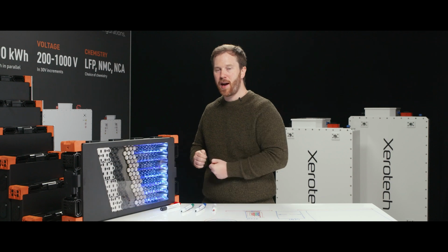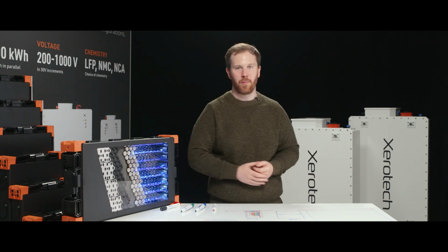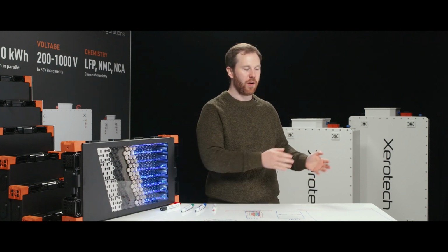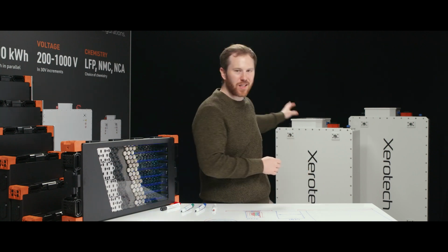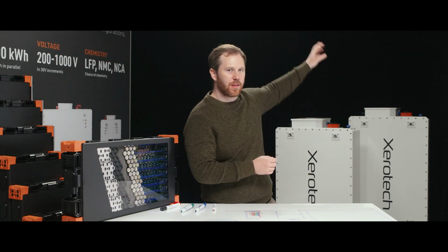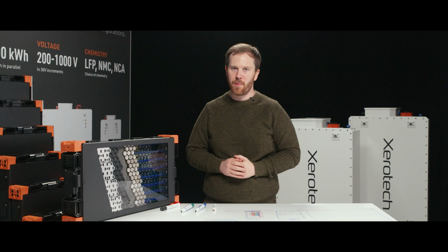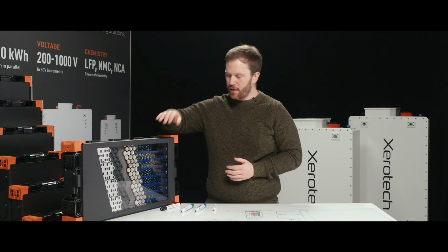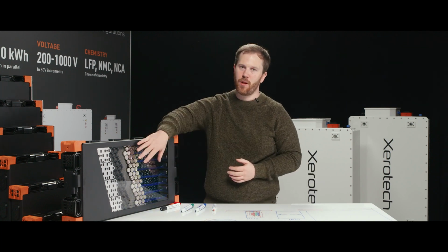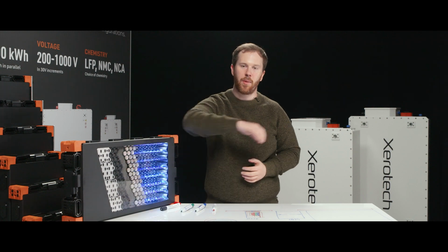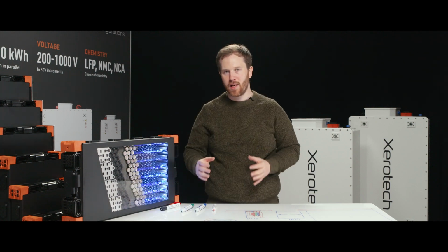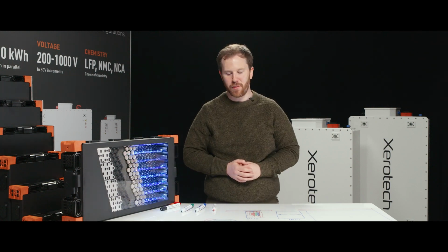Important to point out that very few packs have thermal management in them. What they have is heat exchangers. Heat exchangers get the heat in and out of the pack. A thermal management system like a heat pump, an electric coolant heater, a radiator is all outside of the white box, somewhere else in the system. So that's separate to the battery packs, as are the pumps. So this gives you a super highway in and out of the pack, or in and out of the module, but it's up to the end users typically to get it off their vehicles or out of their systems.